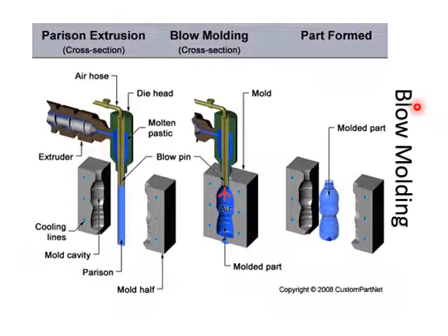This is an example of blow molding for producing a water bottle. So you have the first one, which is the parison extrusion, where you extrude the material from the raw material condition, which is the granule and so on, and then you push it towards a die head over here, and then it will form into the shape of a rod, and then pulled down over here, and then it will be compressed with the molded die.